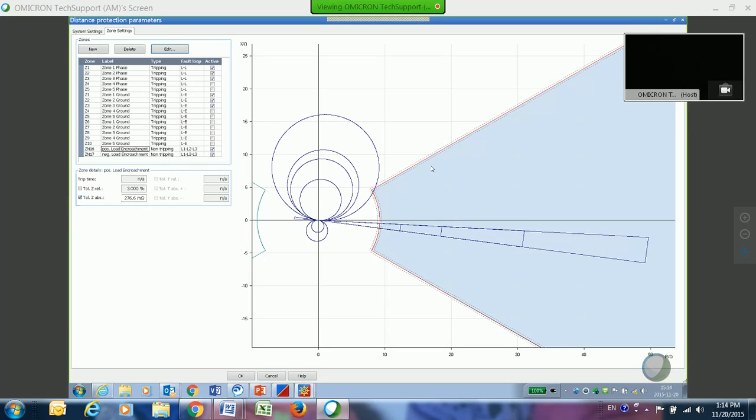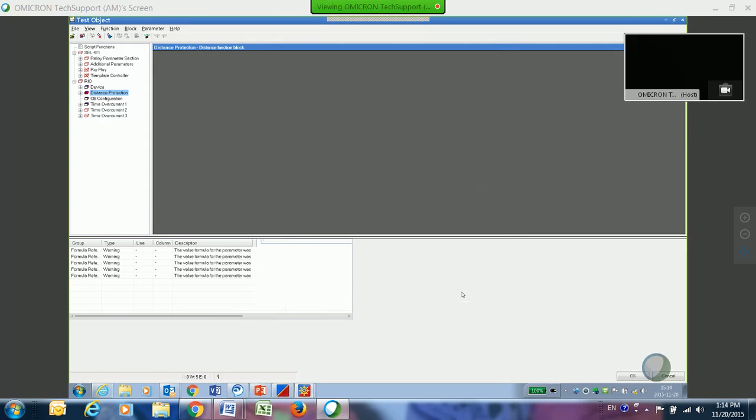Okay. My next question is, if I'm setting both the tolerance values, absolute and relative, which one will be valid in the report? So with my settings there, it basically will use the larger of the two.